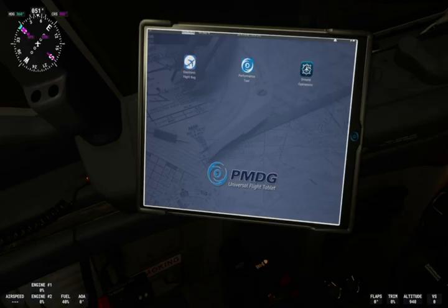Takeoff speeds. V1 150. VR 151. V2 155. 150. 151. 155. Checked. CDU pre-flight. Completed. Rudder aileron trim. Free and 0. Departure briefing. Completed. Anti-collision light. On. Before start checklist completed.